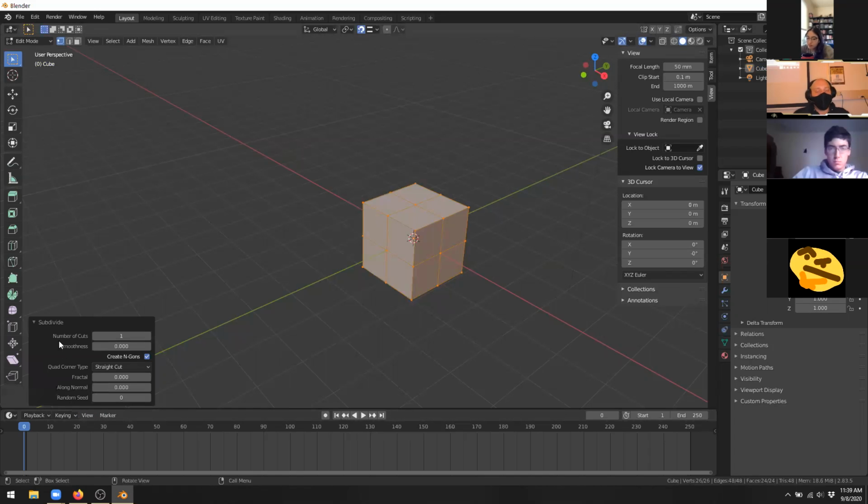There's a little menu down at the bottom left-hand corner of your main interface. And within that menu, you'll see that there's an option for number of cuts. And we can modify that. I'm just increasing it real fast. We can see that I could take the number of cuts that my object has and maybe increase it to 3. And you can see what that does to my subdivision: rather than 2 faces per side, I now have 4 faces per side because it created additional cuts.